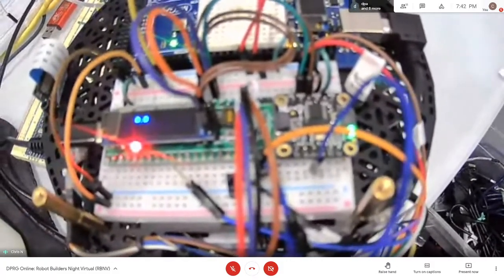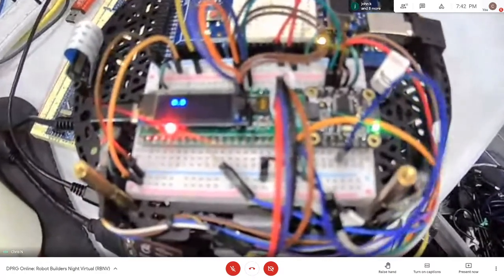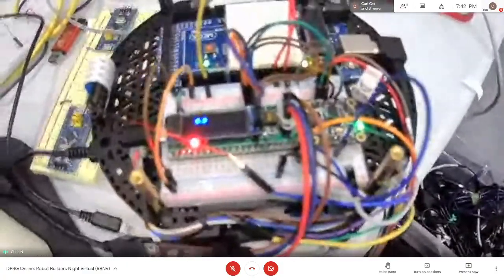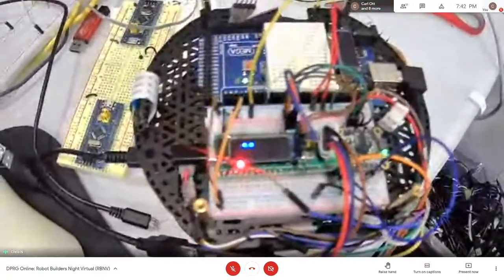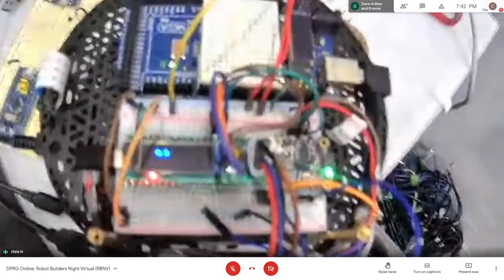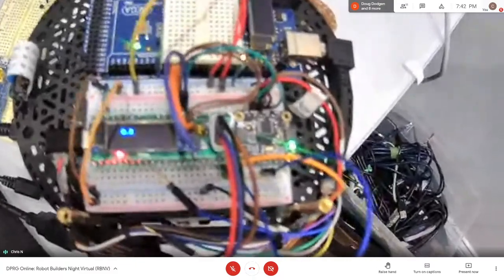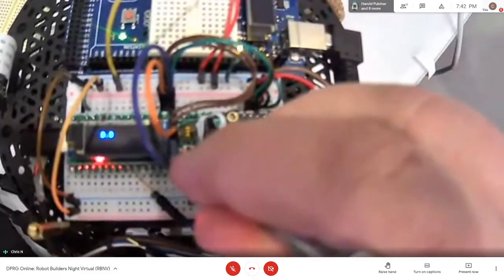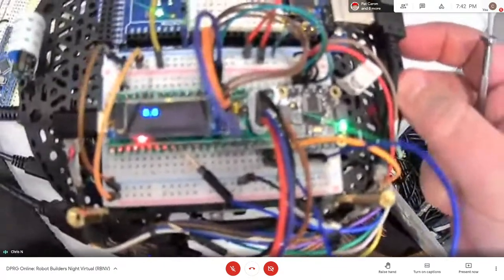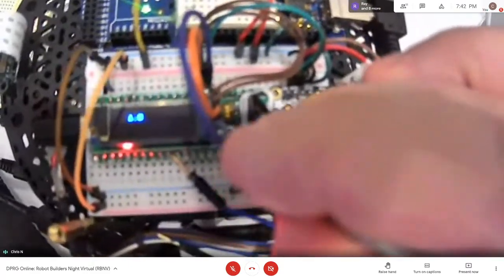When I power up or when I reset the STM, the OLED initializes, it puts "ready" on the screen or something. The moment I let the BNO participate, I don't know what the success rate is of coming out of reset properly or power up, but it's at best 50%. I can hit the reset button here right now. Okay, now we got lucky. You saw a little "ready" flash by maybe, and you can't see the number here, but I'm just displaying the angle, my heading, on the OLED.